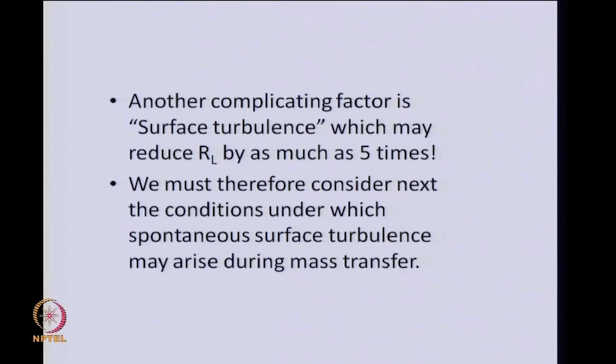What you can do is, you can check this hypothesis, take a glass rod and whip the surface a little bit, disturb it, you would be able to temporarily overcome the effect of oleic acid. There will be fire. Okay. So, here oleic acid, which is otherwise possible to burn, can extinguish fire. I think that answers one of the questions which was raised last time. Can you reduce the evaporation of petroleum products or volatile products? Yes, using suitable monolayers you can increase the interfacial resistance and thereby suppress the vaporization and therefore the inflammability.